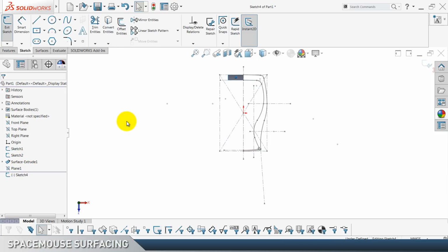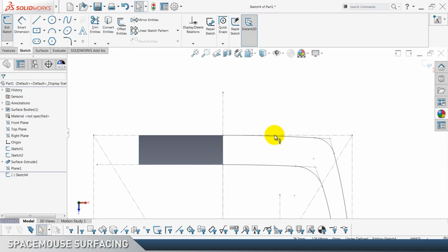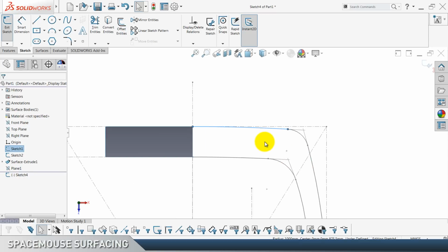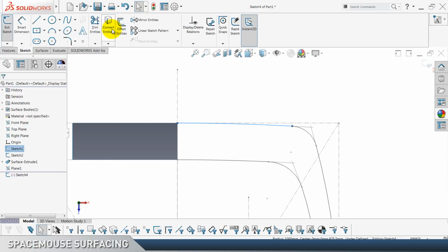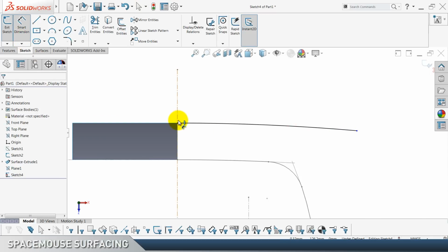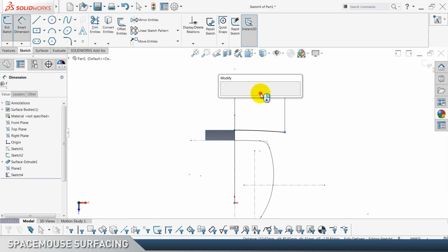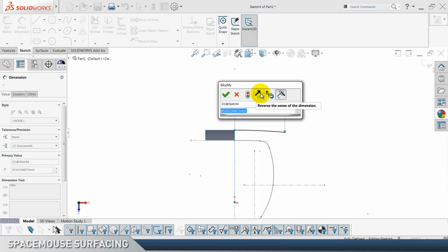Now in this sketch we're going to convert this arc from sketch, it's probably sketch number 1. So convert, and we're going to hide this sketch, extend this a little bit and go from, let's say, origin till this point. We have 90.